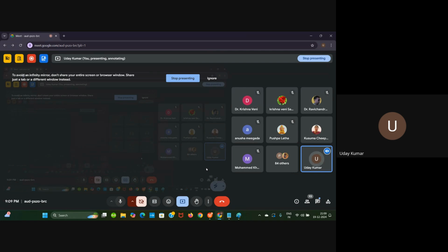What will happen in this way? Wherever you have a setup margin, you are trying to optimize the power by swapping back to HVT. That's how we reduce the leakage power, and simultaneously fix setup and hold. First we had setup violations and we overfixed them, then we got hold violations and we fixed them, and again we got some setup violations, and then we got some power. So everything was balanced.